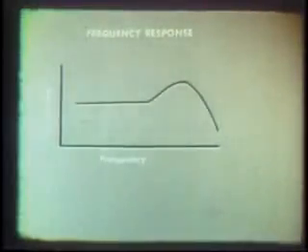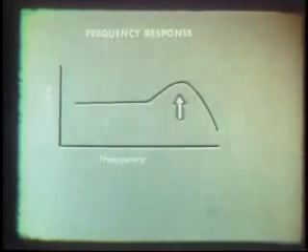Let us now take an opposite effect. This time we'll presume that our amplifier is amplifying the high frequencies more than the rest. Here is the result. The leading edge rises very quickly and actually overshoots the top of the square wave. This is called overshoot.